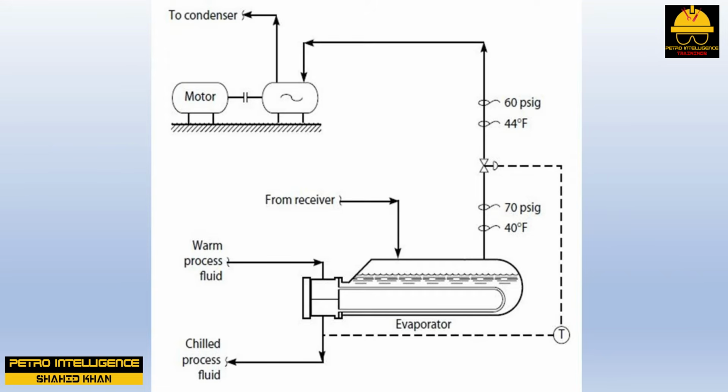And this statement is true regardless of whether the compressor is a reciprocating or centrifugal machine, or fixed or variable speed. It is the condenser temperature that determines the compressor discharge pressure. Lowering the compressor discharge pressure can be achieved by providing cooler water to the refrigerant condenser. But how does this affect the horsepower load or electrical power demand on the compressor's driver? It depends on how much the refrigerant vapor flow increases as the compressor discharge pressure is reduced.